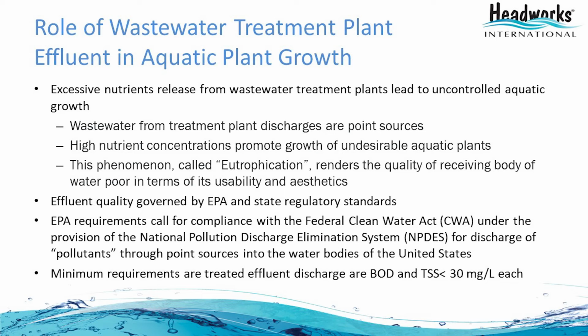A generic requirement for this NPDES permit is BOD and total suspended solids less than 30 milligrams per liter each. But above and beyond that, local regulatory bodies also impose other conditions, most typically on nitrogen, ammonia, total nitrogen, and phosphorus. So we'll look at that.